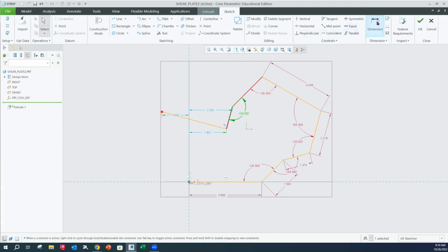So I have to actually add a dimension. I'm going to click, move perpendicular, middle mouse button. This is 2.391. Okay. Ooh, see how this kind of gets a little goofy if you do too many lines at once. That's why I do not suggest going around the entire perimeter, because all of a sudden things are going to start overlapping and folding onto themselves. So a couple segments at a time, because I went 3 or 4 here and it maybe was not the best idea. So I have my 150.